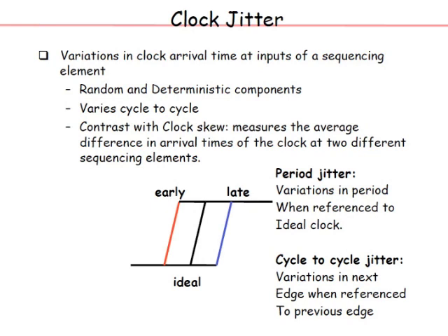There is a difference between drift and randomness. Drift implies a frequency change. Here what we are saying is the clock frequency is, say, 1 gigahertz. The frequency is not changing, it is 1 gigahertz, so you expect the cycle to be 1000 picoseconds. But if you measure every cycle over a period of time, and imagine magically you could measure it, you will find that the cycle is not exactly 1000 every cycle. It might be 999, 998, 999, 1000, 1001, 1002, 1003, back. It will keep on fluctuating.